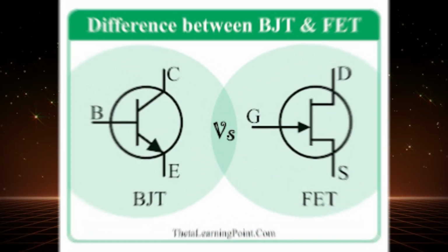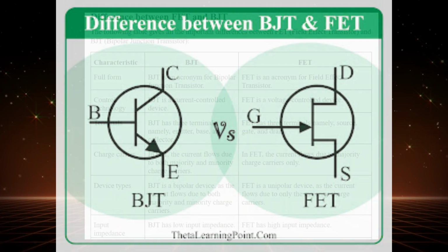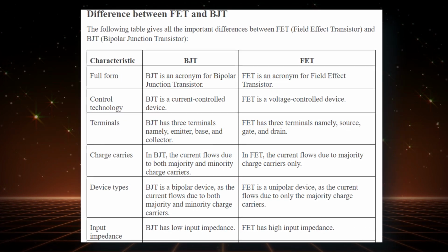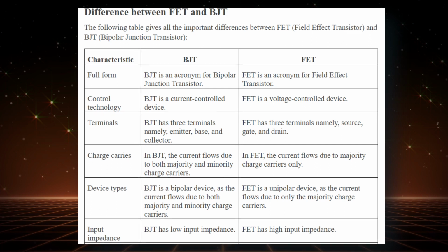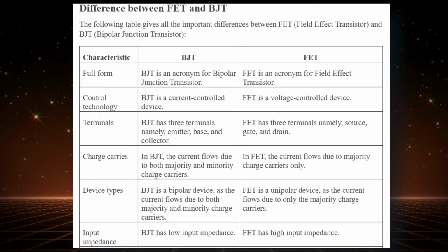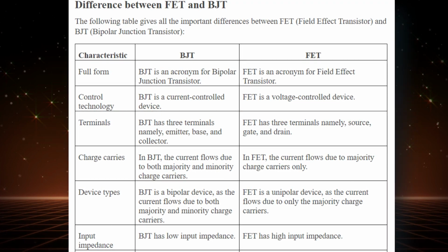There are two types of transistor, the first one is BJT and the other is FET. BJT is a three-terminal device. The subtypes of BJT are NPN and PNP transistors. It is used for amplification of weak signals. In FET, there are JFET and MOSFET. JFET has N-channel JFET and P-channel JFET, and MOSFET also has two types, that is depletion type and enhancement type. Not going into the details of this part, we will discuss the BJT.